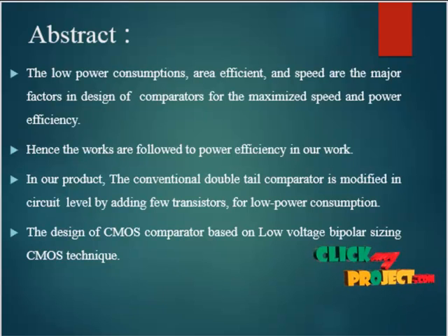In our process we generate a variable delay controlled by a digital word, implemented with a DTC chain of inverters and digitally controlled capacitors. The delay is adjusted by varying the capacitor loading of the inverters. This DTC technique is power hungry, with power consumption increasing linearly with higher resolutions.